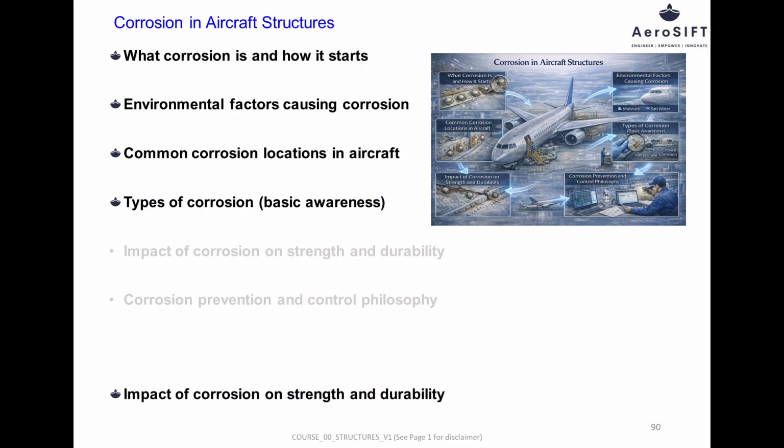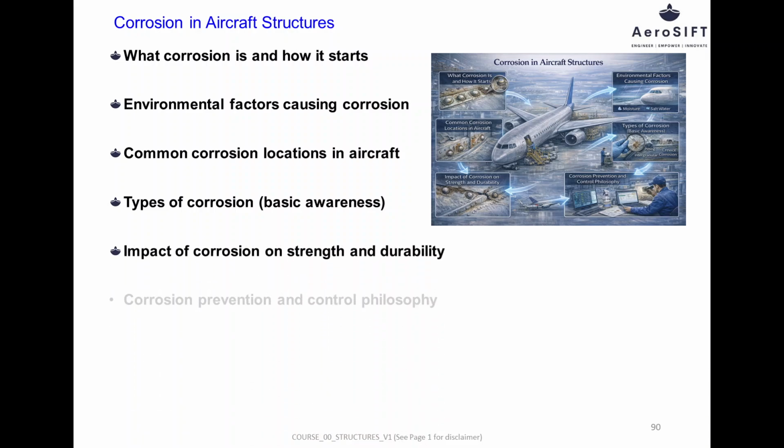Even small corrosion can reduce how much load a part can carry and increase fatigue stress. Pitting and intergranular attack eat away at metal, creating stress raisers that weaken structure and make cracks start sooner under cyclic loads. If corrosion isn't stopped, it can cause material loss, structural weakness, and eventually part failure, potentially grounding aircraft or forcing expensive repairs. Keeping corrosion in check keeps aircraft strong and airworthy.